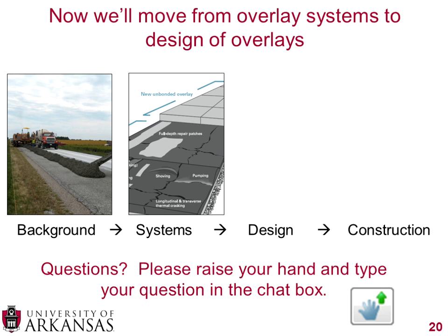So I think with the bonded overlay, the underlying condition is more important, because you are counting on that to handle the structural capacity of the road, whereas with an unbonded layer, you are essentially having 2 different pavement layers and almost 2 separate pavement structures. So I would say with the bonded overlay, the existing pavement condition is more important.